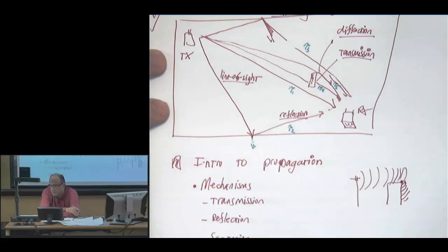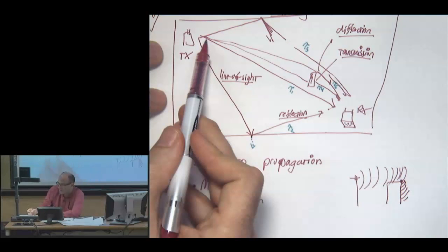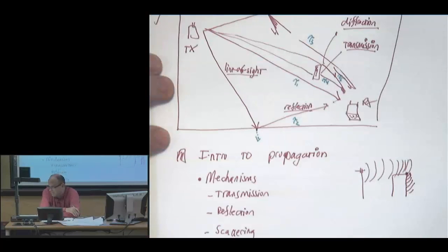So if you remember how we derived the complex baseband equivalent channel, we looked at the two-path channel. This is exactly the two-path channel, line of sight, indirect path here. But then we have to know, what's the difference between the two paths? And then what extra feature we're going to add now, so we want to get away from doing ray tracing. I mean, ray tracing, perfectly valuable area, but just not something from a signal processing perspective that we want to do. So we don't want to model the specific room, the geometry, where you're sitting, what all the seats are made of.